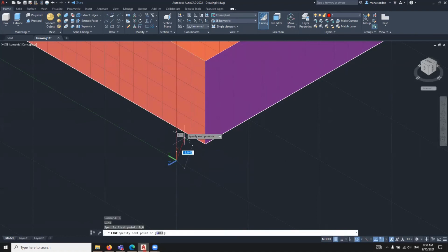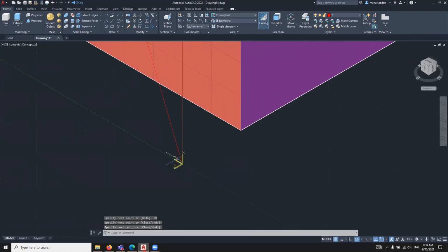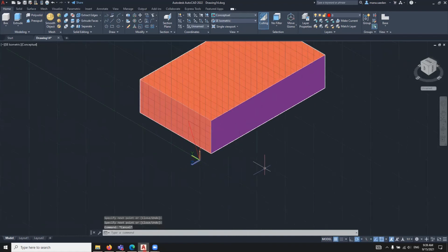Okay, let's start 0, 0, and go up by 50. Go in the y direction by 20, going back here and finish the loop. Okay, now it should be done. We press pull. Now it's worked. Okay, we press pull outward by 40.